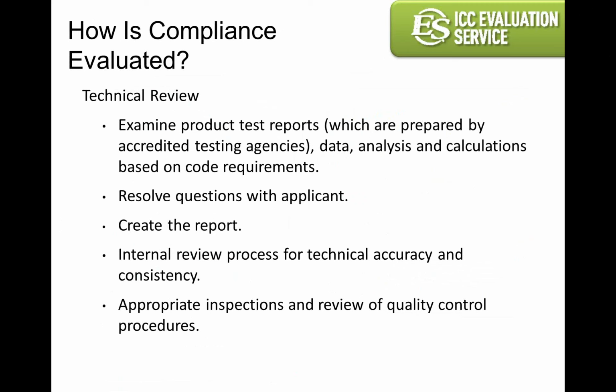So we would have to go in, since there are different makeups of the product. Some manufacturers might use more plastic or a different type of plastic, or more wood, or might be all PVC or something like that. We'd have to go in and look at durability requirements such as freeze-thaw, moisture, UV requirements. So it really gets a little deeper than what you see in the code in a lot of cases because of it being an innovative and new product.